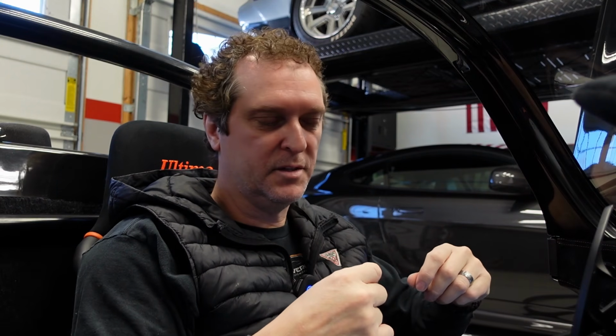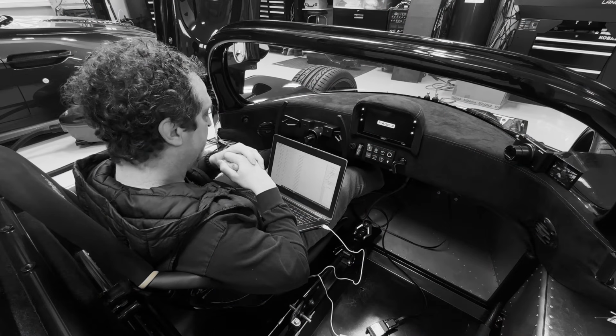So that will add a bunch more noise to the CAN bus. But again, we started with brake switch and throttle, so we have a clue, we have an area. We'll start at looking at CAN ID 105, and maybe we'll get lucky. It's already in there. And that will help us narrow it down much, much more quickly.